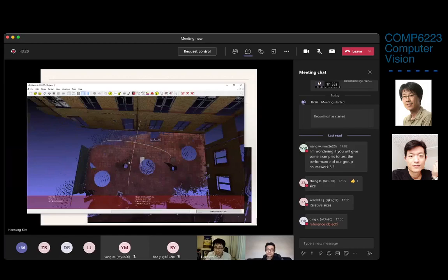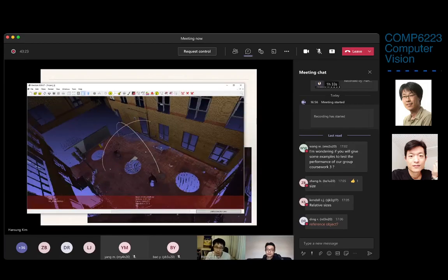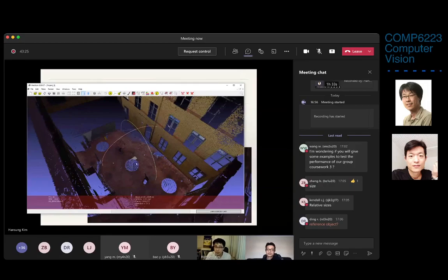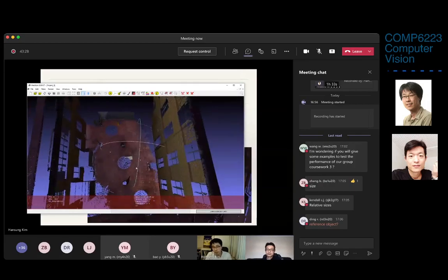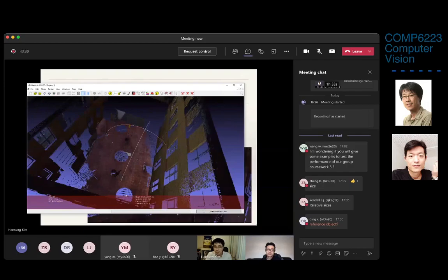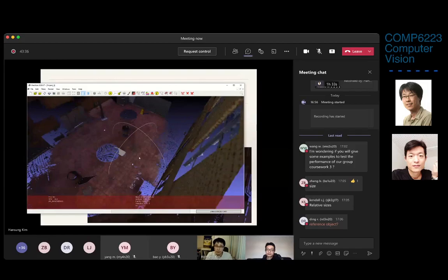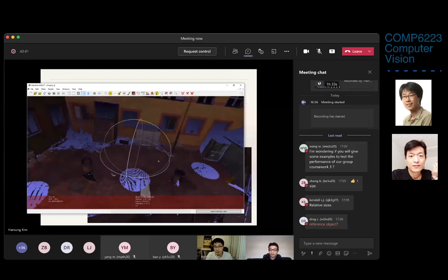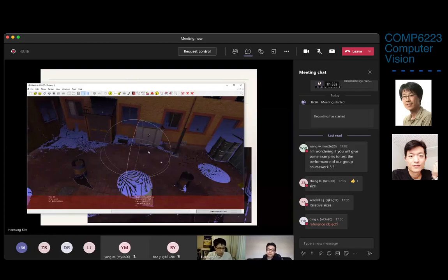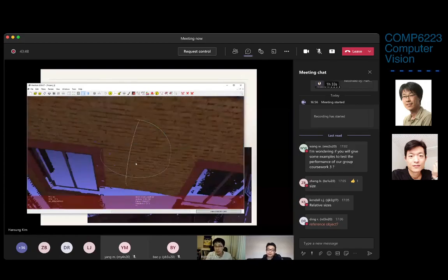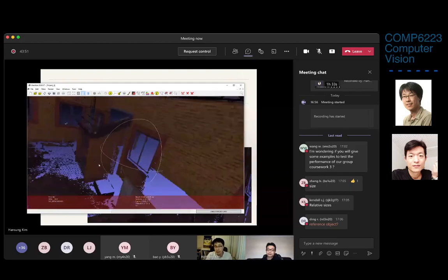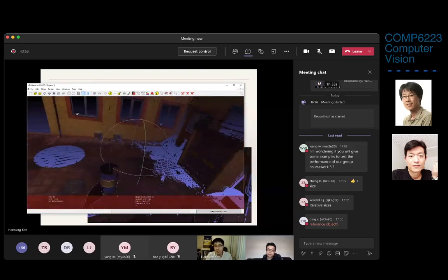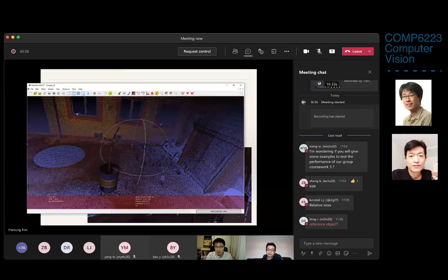This is actually the place I used to work before, and I captured it with LiDAR sensors. There are three holes because I scanned three times because of occlusion. If you scan the scene from here, you cannot really see behind some objects. So I just scanned three times and then registered them all together. And then you can see quite a nice structure of the scene, with some color. They are originally a point cloud, just this kind of dense points.